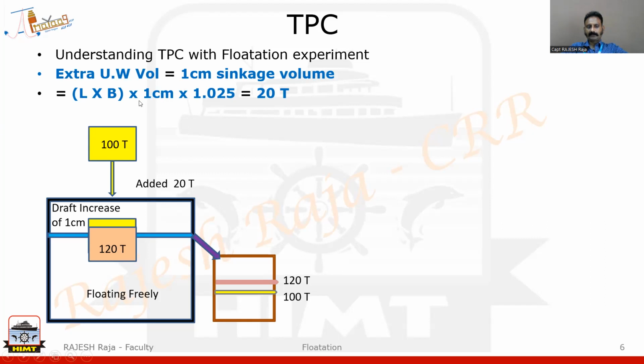So this is that extra volume. So do you agree L into B into that 1 centimeter is the extra sinkage volume. And if I go by my displacement principle, I can multiply the seawater density. Let us say I was floating in the seawater. And let us say that the answer I got was 20 tons. So for me, right now, TPC is 20 tons.